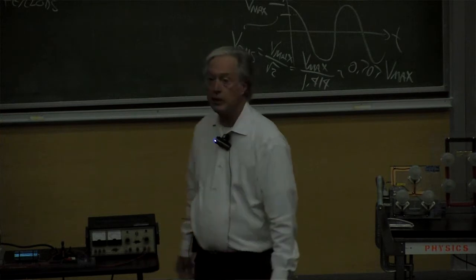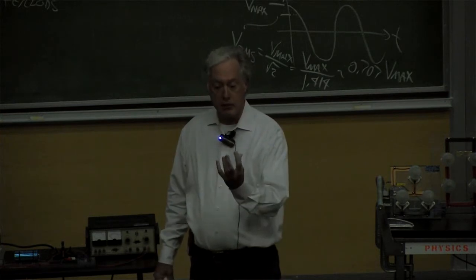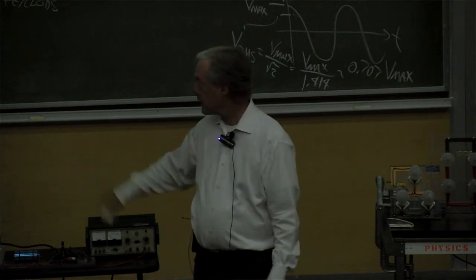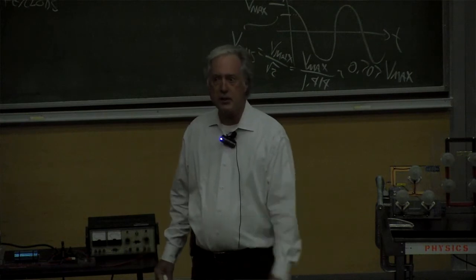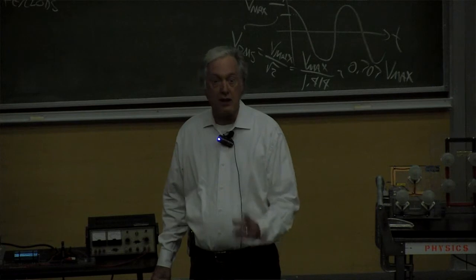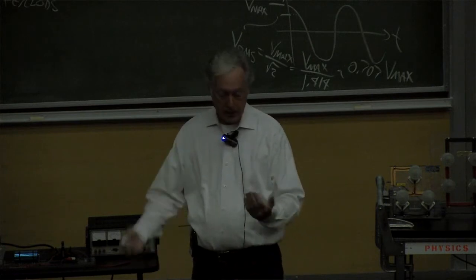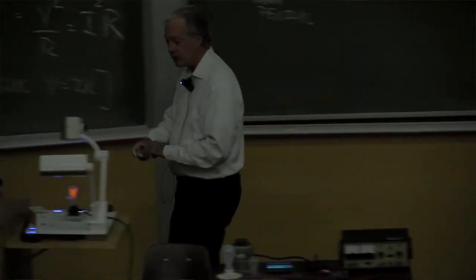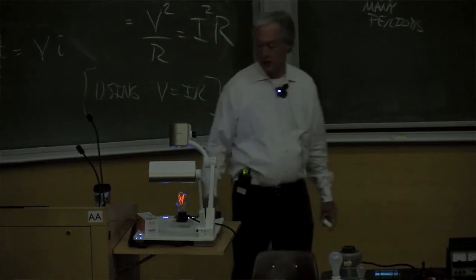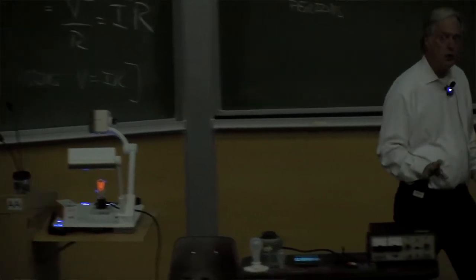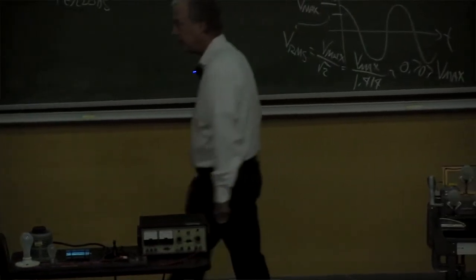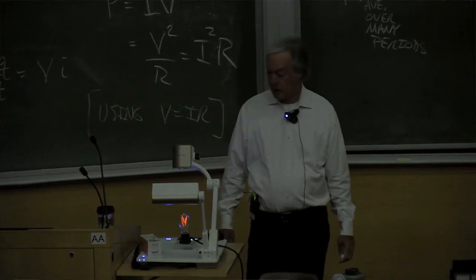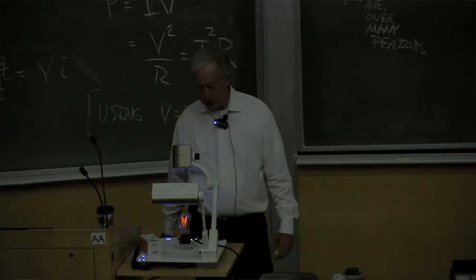Another thing that the glass does is it allows a different environment around the filament for the filament's purposes. If you heat something up really hot, commonly things burn, don't they? Or they oxidize. They change their property by interacting with the gas around them. So if you took a light bulb and you filled it with argon instead of air, then argon is very inert. It doesn't do much in the way of chemical reactions with things. And if you heat the filament up, you're going to not oxidize its surface, and it'll last a long time. So the glass bulb serves several purposes.